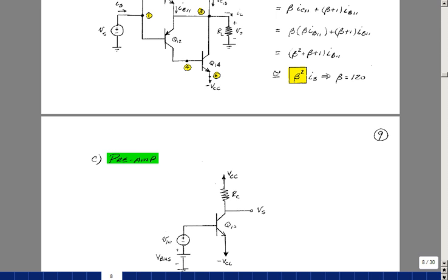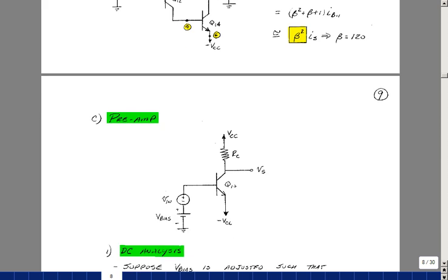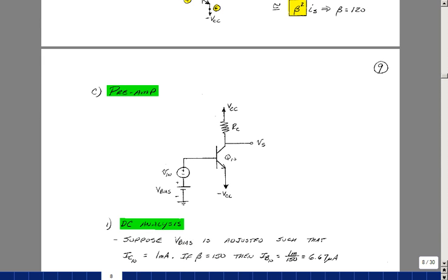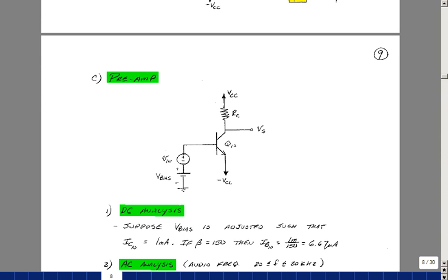The voltage gain of the power amplifier, as we saw, was approximately 1. So if we're going to try to boost our signal from the AM or FM part of the radio, we'll need to have a preamp with the power amplifier so we can get some voltage gain besides just current gain. Just look at a simple one transistor scheme.